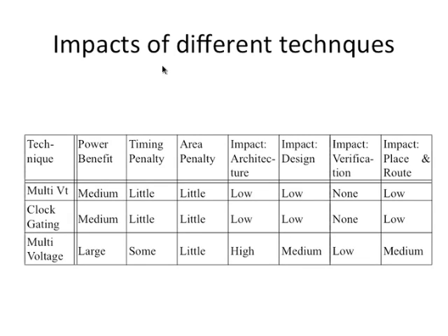Finally, if you look at these three techniques which we have looked at, what are their impacts? If you look at the clock gating technique, basically this is a qualitative kind of rating: medium. Again, it depends on how much power dissipation is due to the clock and what fraction of the clock network you can gate. It really depends on the kind of chip you have, the kind of computations you're doing and so on. So basically the authors say here that it's about medium.